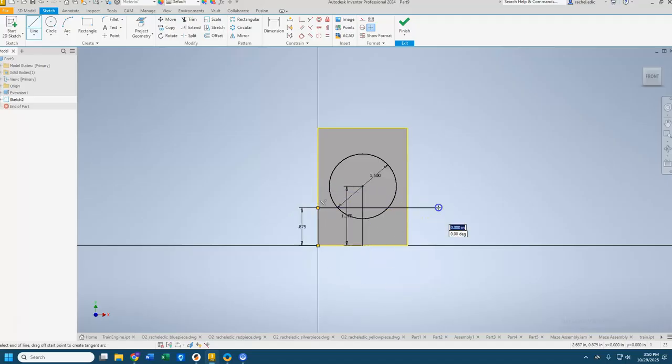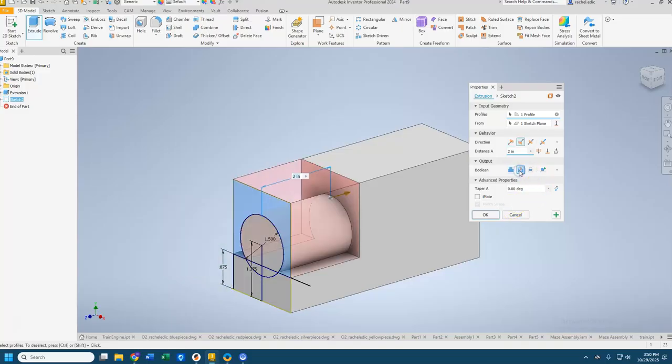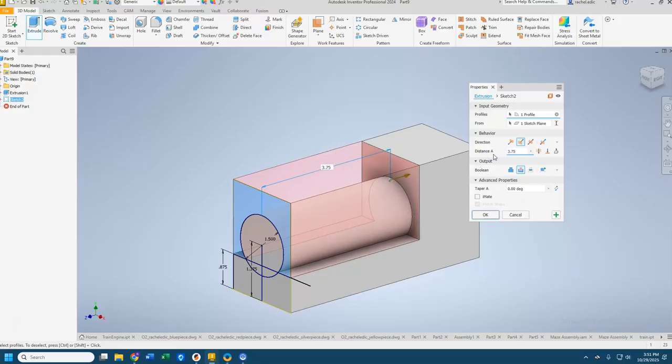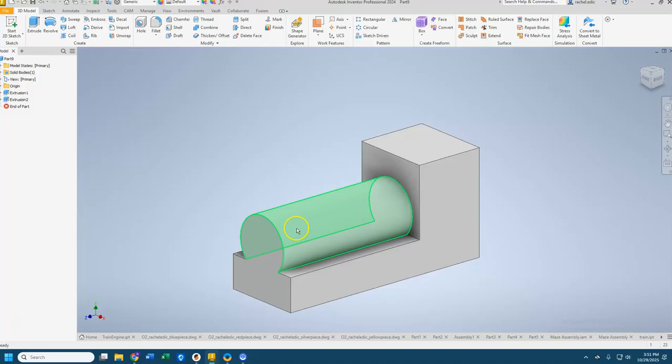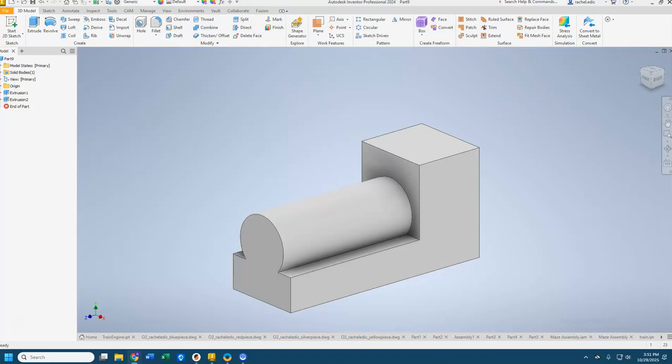Again, this is not a 100% step-by-step instruction. It's just to give you something to start with. So I'm going to extrude, cut that. I cannot do mental math in my head, so I do need to use a calculator to do some of these calculations. So there, I've extruded that, leaving only 1.75 back here. That's what I was doing. My total length is 5.5, and then from here to the end is 1.75. So you need to calculate how far that extrusion is going to cut.